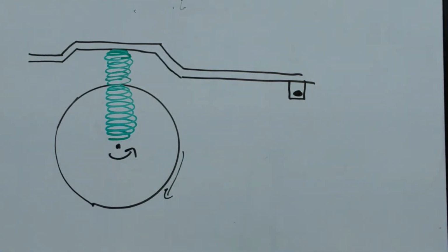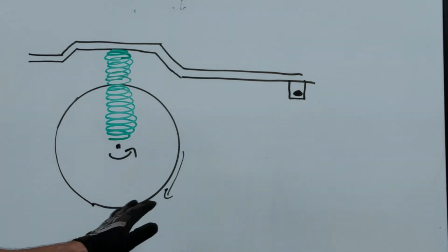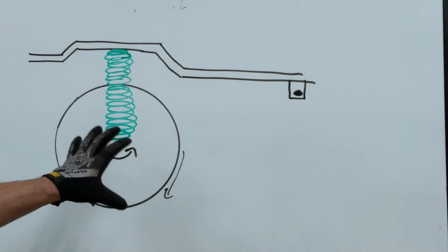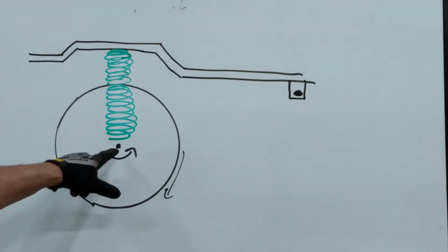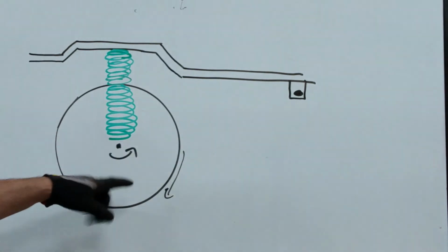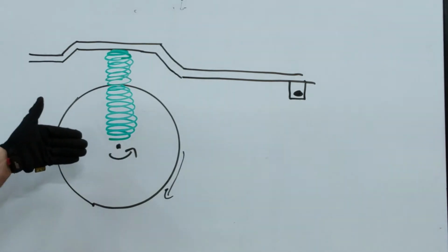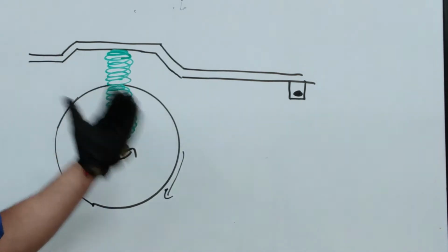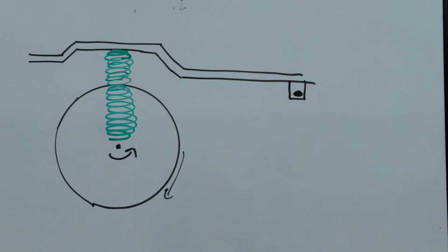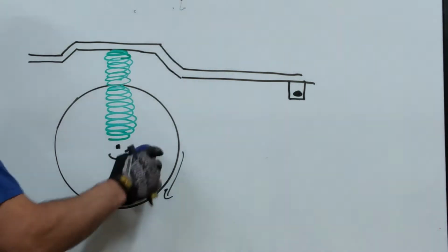So with these forces, rather than the forces acting just from the brakes, but when we have torque forces being supplied to the tire to propel the vehicle forward, the axle on the vehicle wants to go in the opposite direction. A coil spring is not going to stabilize that. The coil spring needs some help. And through the addition of some links, that's very possible.